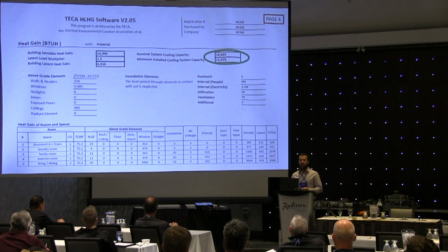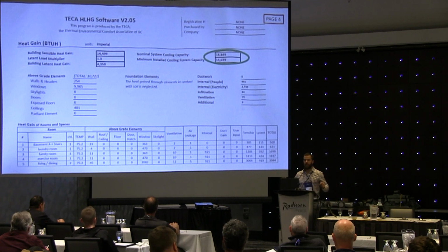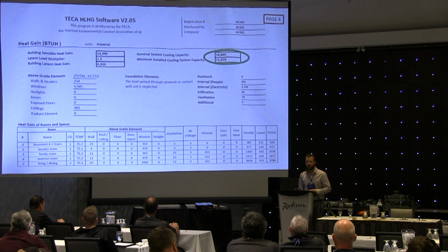You might be thinking of radiant heat coming through a window, adding heat to the room directly, not necessarily through the envelope. And that is a type of loading, but it's considered in the windows. It's considered an above grade element. Anyone else? Internal loads for cooling. We didn't see that for heating. It's got to do with whether it's livable area or not. Are people in there, appliances, things like that. Yep, you're completely right.